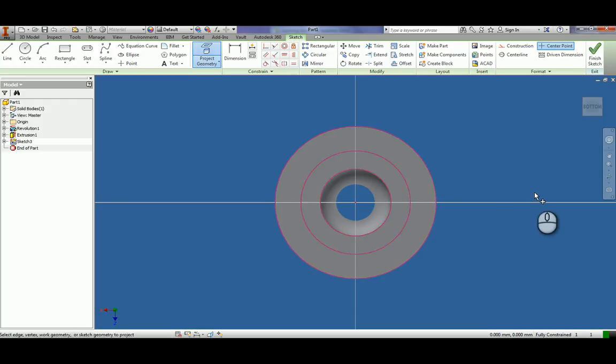and now you're going to put holes in here after you make 2 reference lines for your dimensions. So you're going to do construction, put one here, put one here. You can change what a line is by clicking on it or selecting it and then clicking in the top right hand what you want it to be. We're going to want these to be a certain angle apart, so we're going to click both of them. And then we're going to put in 110, which is the angle we want.